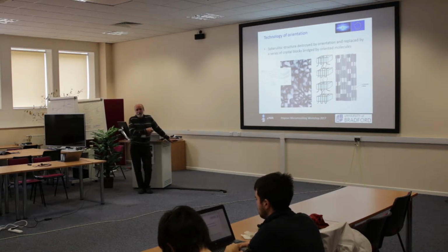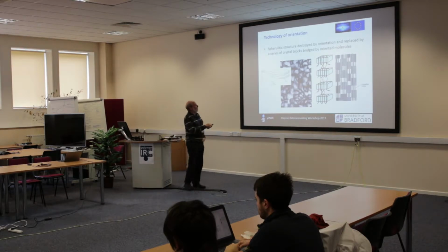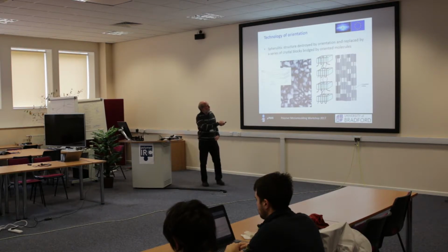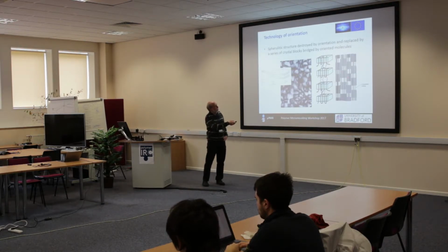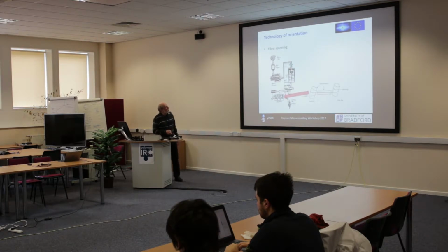If you draw the polymer, then you'll destroy the spherulitic structure and create a different structure. It creates a more fibrillar-type structure. It looks more like this, and you end up with a self-supporting, really, a kind of network of polymer structure that is known as a crystal bridge type of structure, where the dark parts are crystals, and there's some continuity as you go across the material. So that's the basics of it.